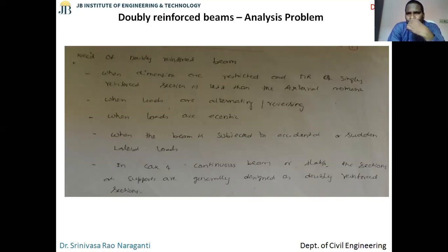Sir, once explain the first point, sir. Yes, when the dimensions are restricted. For example, on site when you construct beams, you will not have enough space to increase the width or depth because of site conditions. Maybe you want a clear height somewhere, or there is an adjacent property and your land boundary, so you can't increase the dimensions of the beam. Or you have some construction issues. You can't have infinite width or infinite depth.